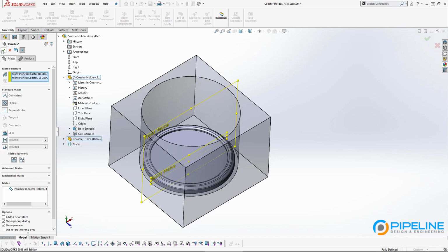Yeah, especially in this conversation about keeping things from rotating, I almost exclusively use parallel because you're usually putting a screw through a hole, or a washer on a screw, and you're going to be using a concentric mate, so I always just use parallel. Got it. Great.